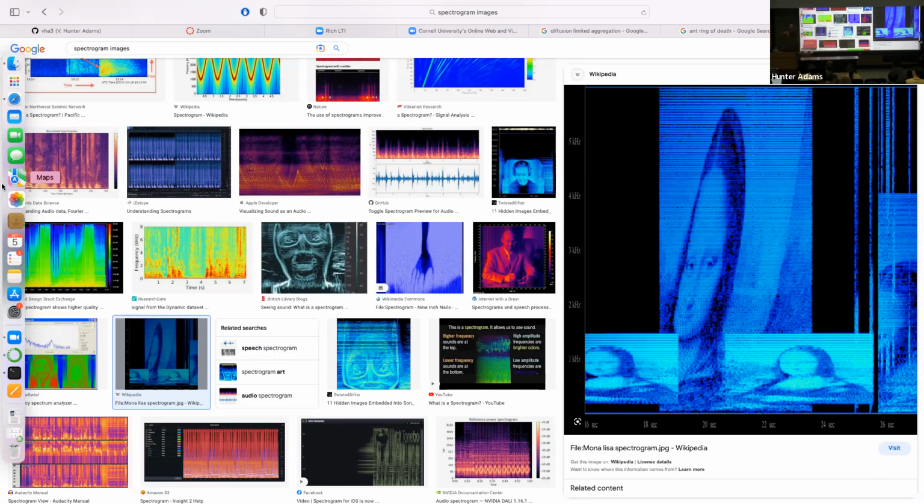And then you take the power in that range of frequencies and you use it to set the amplitude of a direct digital synthesizer at the center of that band and play it back. And what you can end up with is a sort of weird synthesized version of a human voice. And the fewer synthesizers that you have, the more strange and sing-songy it becomes. Does anyone have an intuition for how few frequencies you require in order for the voice to still be understandable?